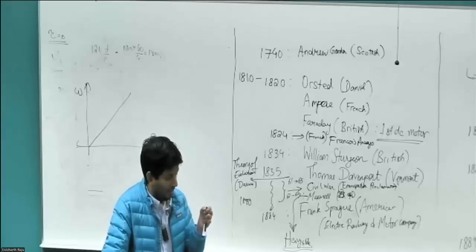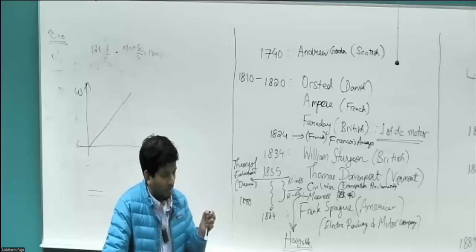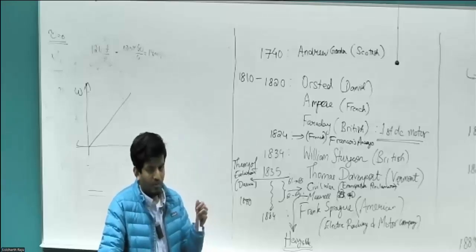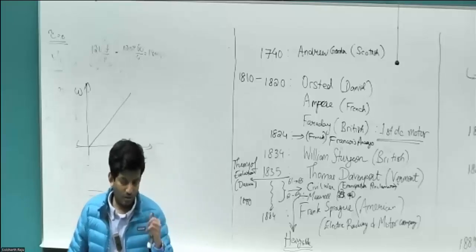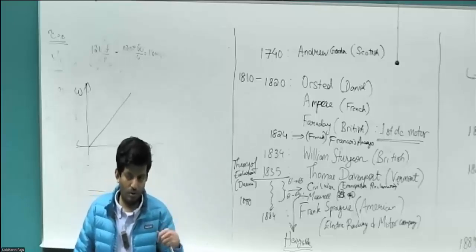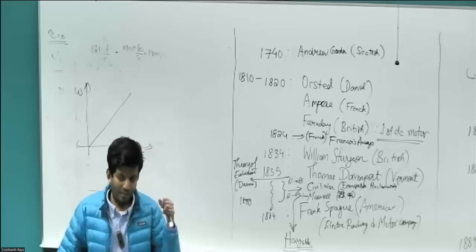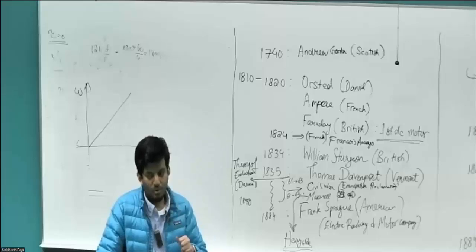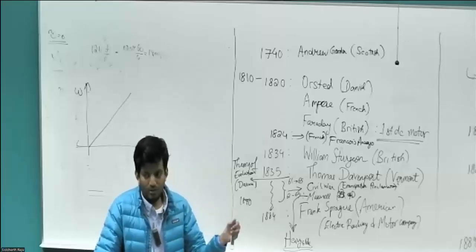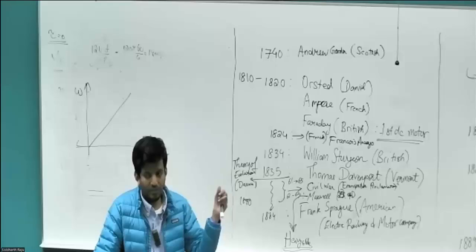The reason power electronic converters help is because if the rotor comes to a stop, the converter can detect it and then stop applying the voltage, right? And if the load torque becomes low enough that the motor can spin up again, it can start applying very low voltage at very low frequency and then gradually ramp it up all over again. When you connect it directly to the grid, you don't have that option. It's always the given voltage at the given frequency.